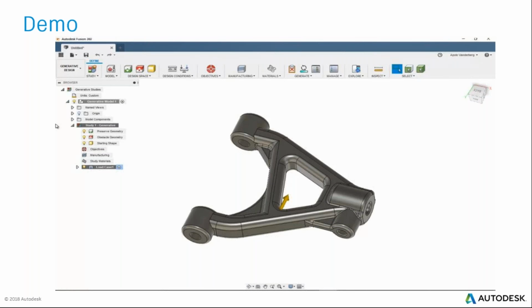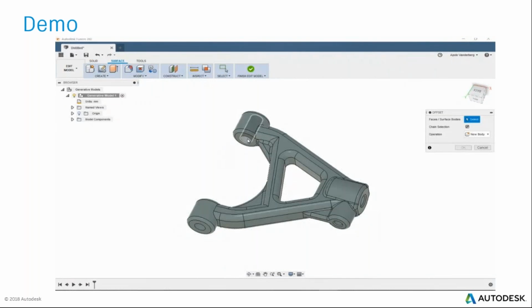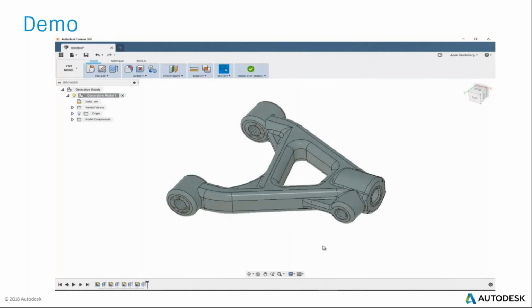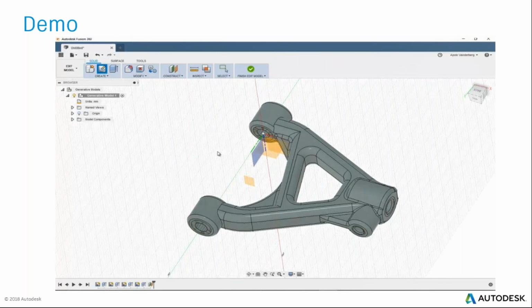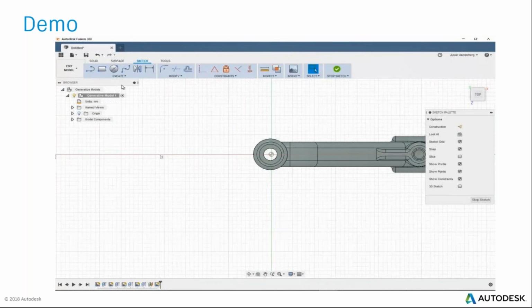There were a couple where, given the orientation of this A-arm, when we did our additive print, we were assuming we were flat on the print bed, and then we printed vertically, in this case in the Z direction, to get that geometry.